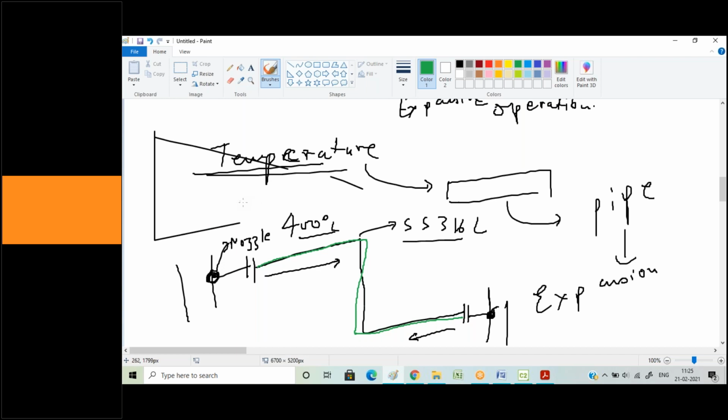I mean the displacement might not be that big, how it's looking. You can say it's a magnified view, in order to get a clear picture of the movement. So I have increased the scale of my deflection. Now what is happening? The movement of this pipe in this direction is actually pulling my nozzle.